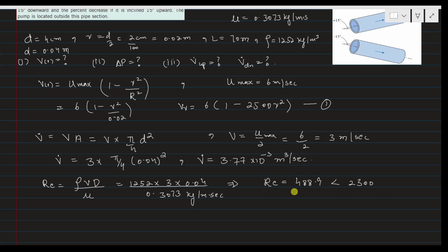It is always that glycerin is very viscous, and it is flowing at a very low velocity. So it is obvious that the Reynolds number must be less than 2300, and it comes under the domain of the laminar formula. Now to find the friction coefficient in case of laminar flow, that is 64 divided by Reynolds number.